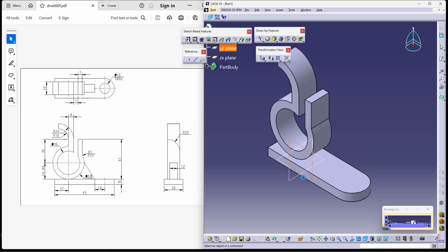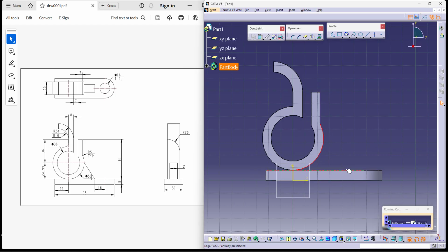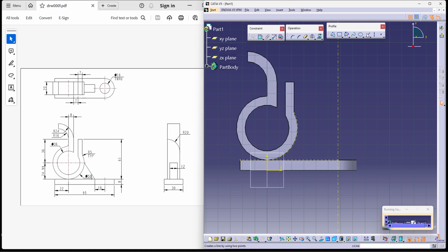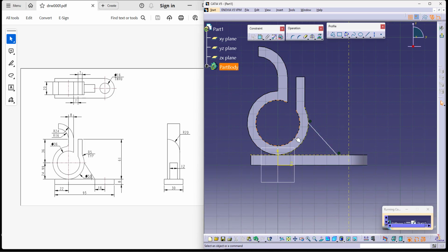Again, I'm selecting the sketch. Again, I'm trying to make it. These two are my references. And of course, the axis. Now let's start making a line. This is the support which we are supposed to make. Now the support should be lying exactly at the center, so I'd like to use this again as the center and then take my reference, which is a horizontal line, and then try to coincide the dimensions, coincide the line, maintain the dimensions, of course. Now the dimension should be maintained from this end to this, since it is supposed to be 16.